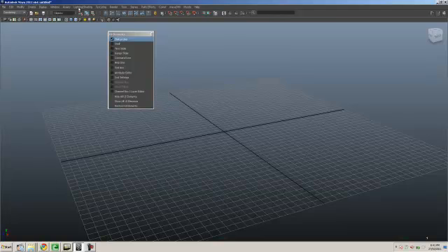And remember, I told you about the menu set. Right now we're in the rendering menu set. If we go to animation, you'll see that things right after assets change. Polygons is for modeling. This is for animation, an animation menu set. Surfaces is again modeling, a different kind called NURBS modeling. Dynamics is where you do your particles, visual effects and various other simulation. Rendering is another menu set which will help you do light, texture, and finally render based on your settings.